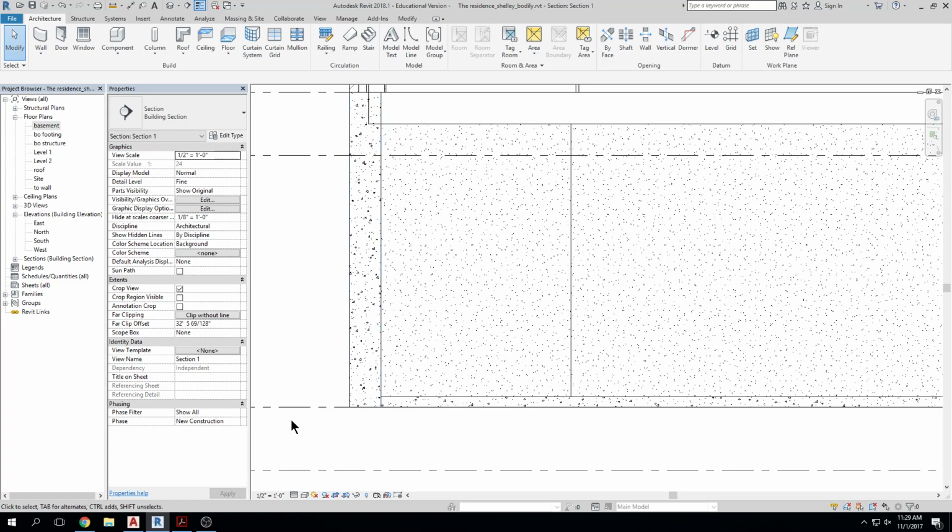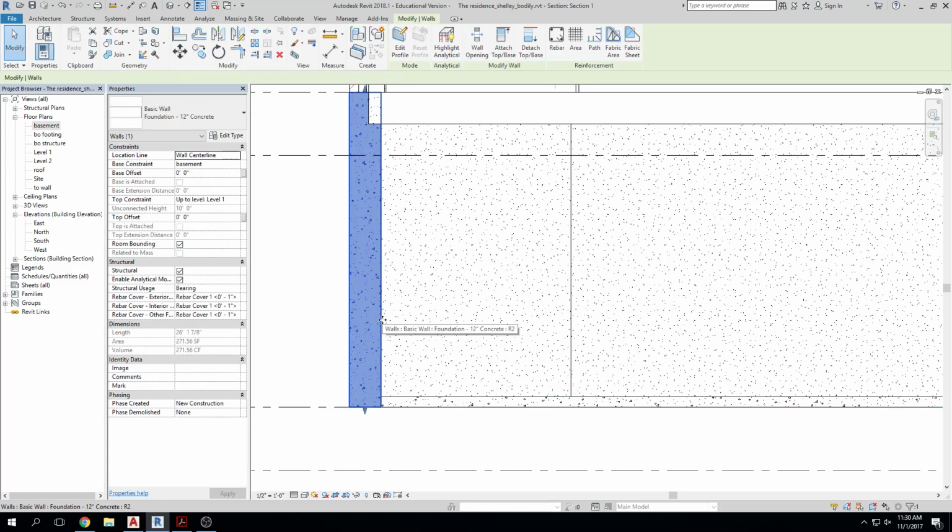But essentially we're going to create a wall type for our footings, and in the wall type you're going to make the thickness of your wall. So this dimension, right? It's going to be very thick. If this is 12 inches, let's add 8 inches on either side of that, so 16 inches, so 28 inches. We'll have a 28-inch thick footing, right? Write that down. If you had an 8-inch concrete wall for your foundation, maybe it would be 2 feet wide or whatever, okay?